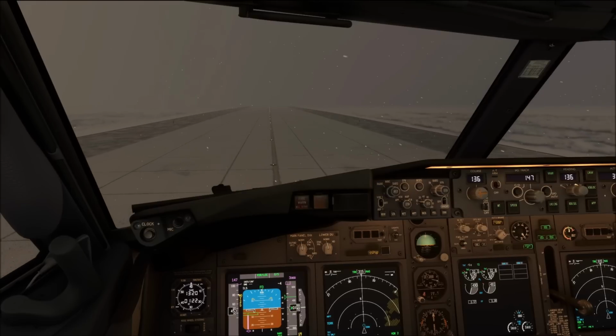The runway was so slippery towards its end that the entire aircraft just slipped over the runway end and it was impossible to brake it to a standstill, even though they were just at 30 knots and they had about 500 meters of runway remaining at that point. Full wheel brakes did nothing, the thrust reversers took far too long to come out, and that's how in the end they slipped off the runway and ended up in the grass and the approach light system.